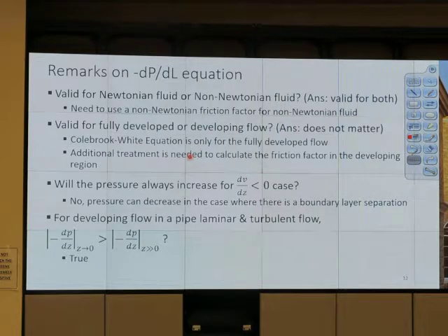Okay. So when it's high viscosity, it doesn't need to be non-Newtonian fluid. It can be Newtonian fluid, for example, honey. Something that is non-Newtonian fluid can work like an elastic band. If you see it move back and forth like this, that's non-Newtonian. So this means it can store some energy and bounce back, right? Another example is shear thinning and shear thickening, Bingham plastic. Bingham plastic means we need a certain pressure to push it, otherwise it doesn't move. Shear thinning means when we flow faster, it becomes less viscous. Shear thickening means when we apply force or flow faster, it becomes more viscous. Hong, what is the example of shear thickening?